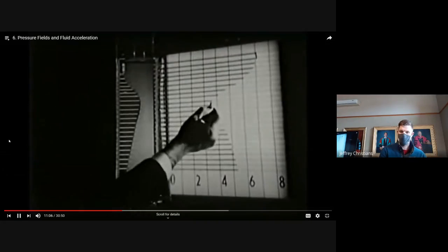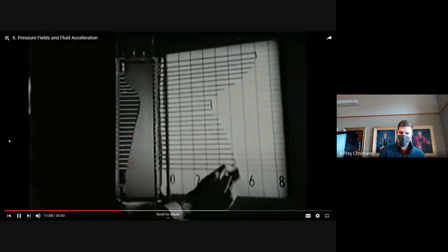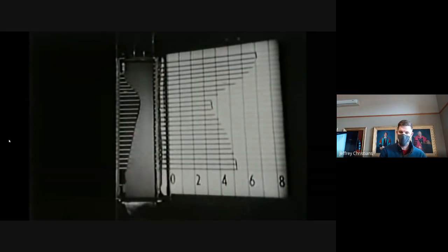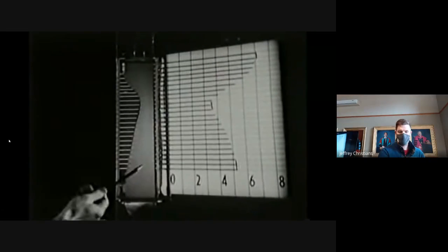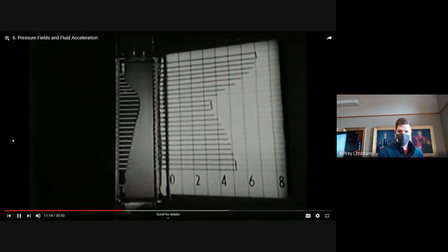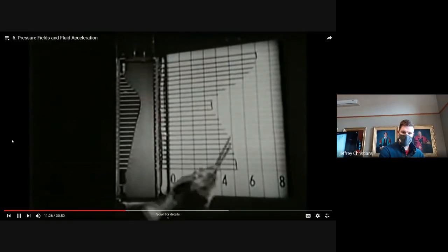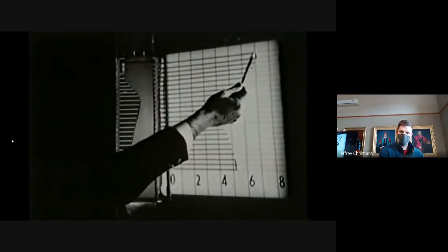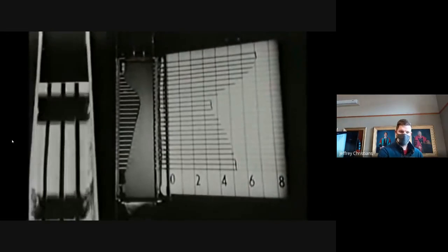At the upstream and downstream ends, where the cross-sectional areas are equal, the average velocities are also equal, and Bernoulli's integral will predict equal pressures. But the downstream pressure is actually somewhat less than the upstream pressure. This difference is due to viscous boundary layers, whose behavior we must always keep in mind, even when we pretend viscosity is absent.